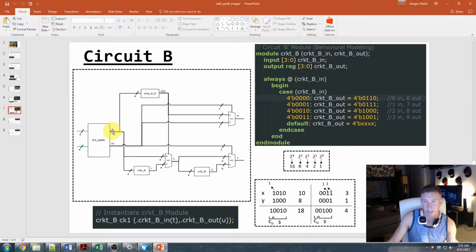So if we see that, our carryout is a 0, right? So that's going to be selecting whatever input is on this line. And our sum is going to be 4, right? So that's going to be less than 9, so that's going to choose this input. Whatever that is, it's going to be output to this t here. And since we know there's no carry out, because that's the select on this next MUX, it's going to just carry through to the next one.